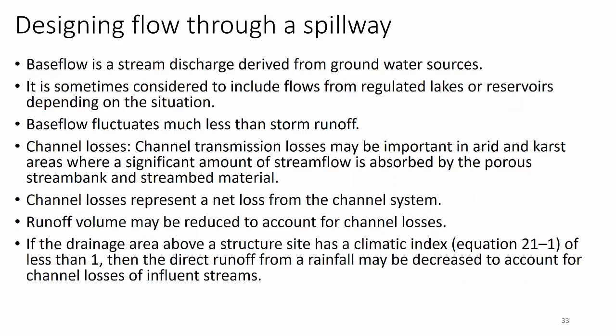So base flow is a stream discharge derived from groundwater sources or interflow. It's sometimes considered to include flows from regulated lakes or reservoirs, depending on the situation. You've got to know your situation, know what your base flow is made of. It fluctuates much less than storm runoff.